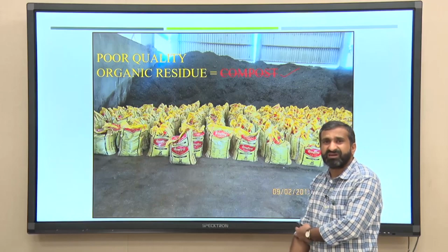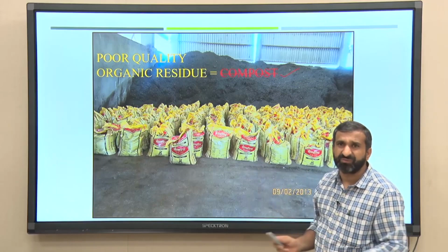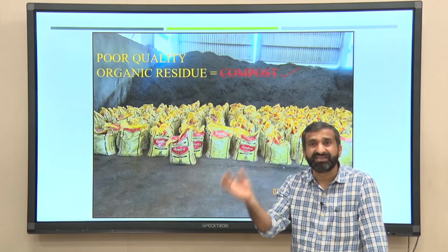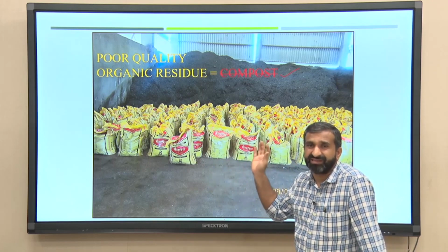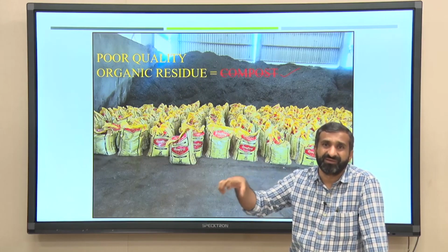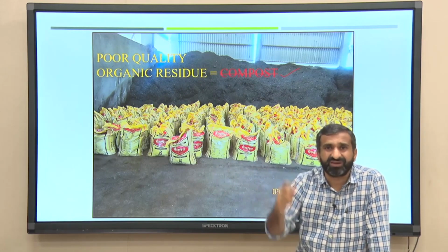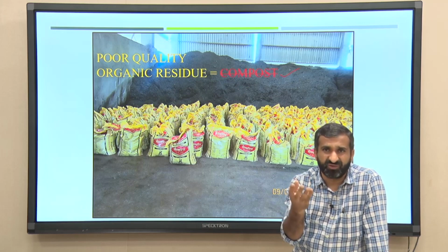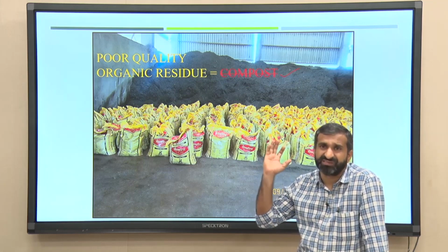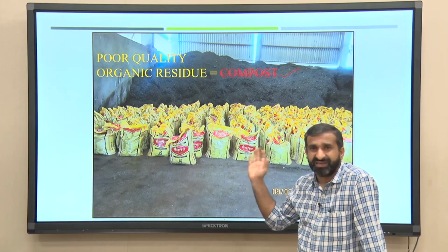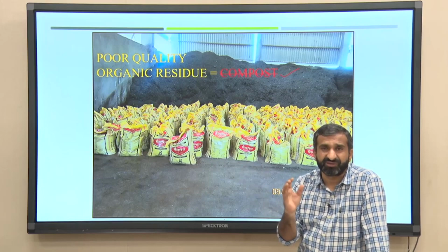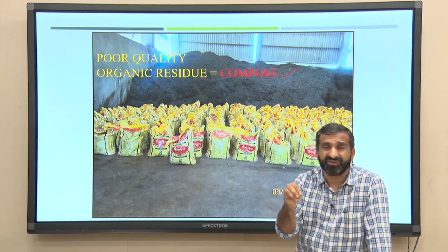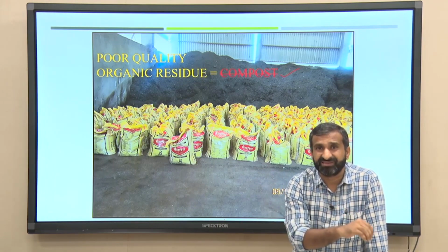I think these kinds of units, similar trommel composting facilities, are available in many cities. These composting plants are normally called mechanical composting plants. Why are they called mechanical compost plants? Because mechanical units are available, the filter units called trommels, and the cost of each trommel, as per my information, goes to 40 lakhs, 50 lakhs rupees, which is a very costly unit. This facility, with only 50 tons per day capacity, also requires around 8 to 10 crore rupees, not including the cost of space or land.